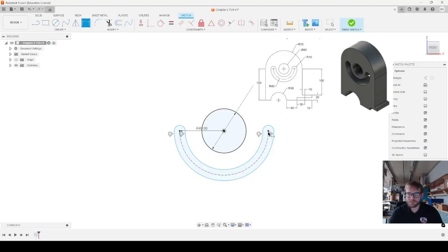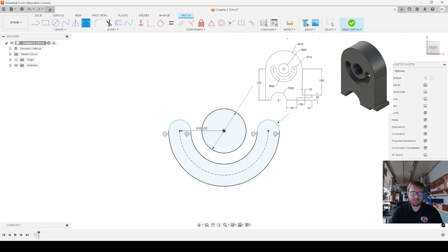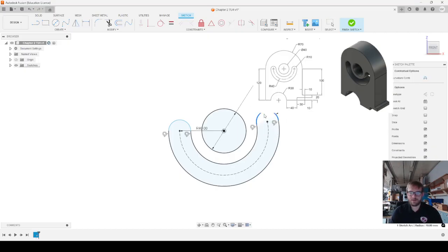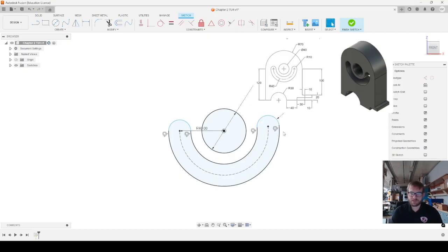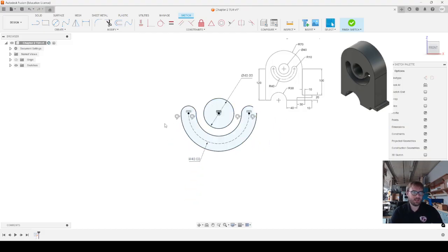That didn't actually lock in the 10 millimeter radius though. So I'm going to click that on one of these circles, and that actually did that a little better now. Notice I can still move this around. So I need to define these 3 points as all horizontal with each other. And then that locks that as black and fully defined. So we have a radius 10, our radius here of this line 40. I'm just putting them similar to where they are in the picture.